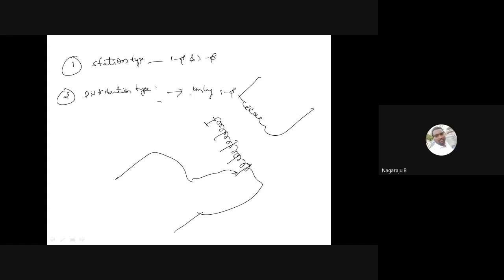In addition to its automatic auto transformer component, a step type of voltage regulator also has two major components, namely tap changing and control mechanism. Each voltage regulator consists of necessary controls and accessories, which have the automatic tap changer, and a voltage sensing control to maintain a predetermined output voltage by receiving its inputs from PTs and CTs.